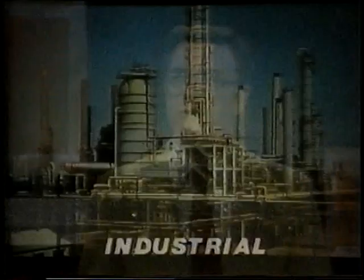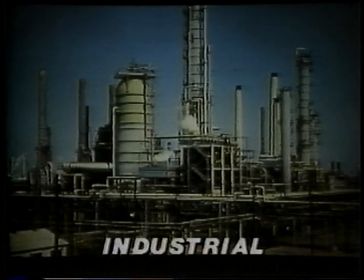What we'd like to do is go through some examples here where we're going to talk about corrosion in some important specific environments and leave it to you to follow up in the environments that are most important in your particular instance. First, we'll talk about the classification of atmospheric corrosion. We can break the entire field of atmospheric corrosion down into several types based on the type of atmosphere that we're exposing the metal to. And we can break that down into industrial, marine, and rural.